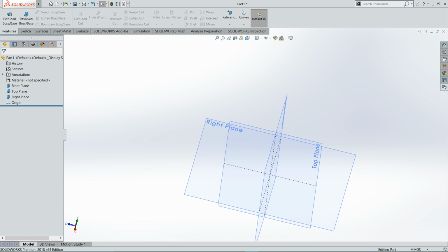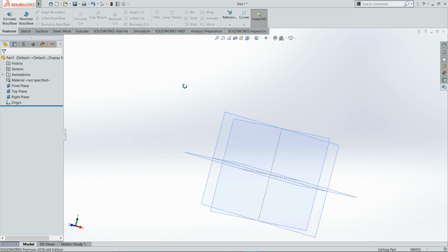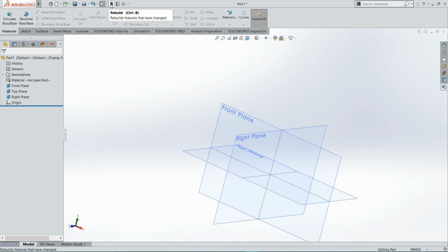Here it is the quick access toolbar that we have seen: saving. You can save all. It is a small part, like publish eDrawings, which is a third-party software. It is SolidWorks software, and you can print it. Here there is undo and redo. Rebuild: if some dimensions are not reflected, you can rebuild it. Some file properties are there.